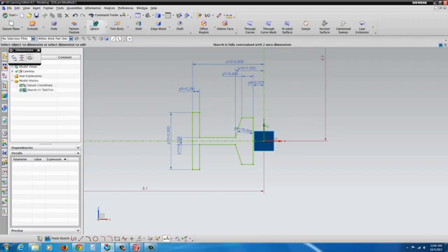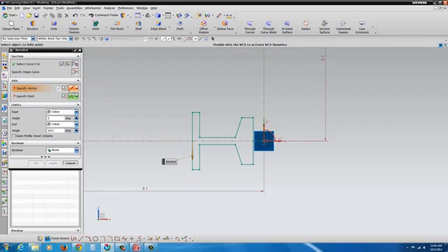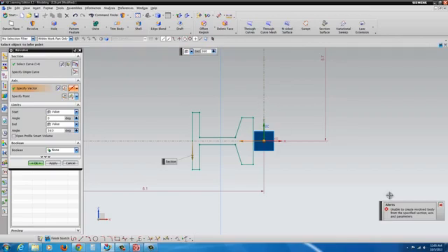So we can go to the revolve button, which is just to the right of the extrude. Go to revolve. From here, it already has our sketch selected, so we can just select 2 points. There are several ways you can do this, but we're going to go by the 2-point method. And we're ready to select the bottom of this. So I'll click on it up here, just to the right of the extrude.